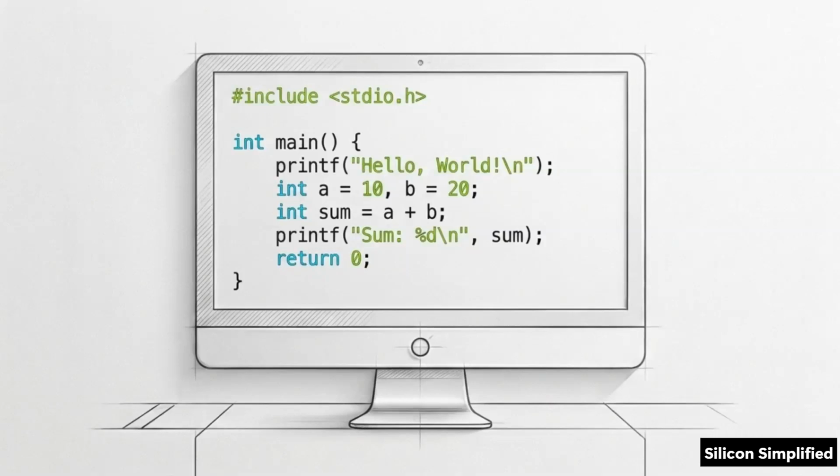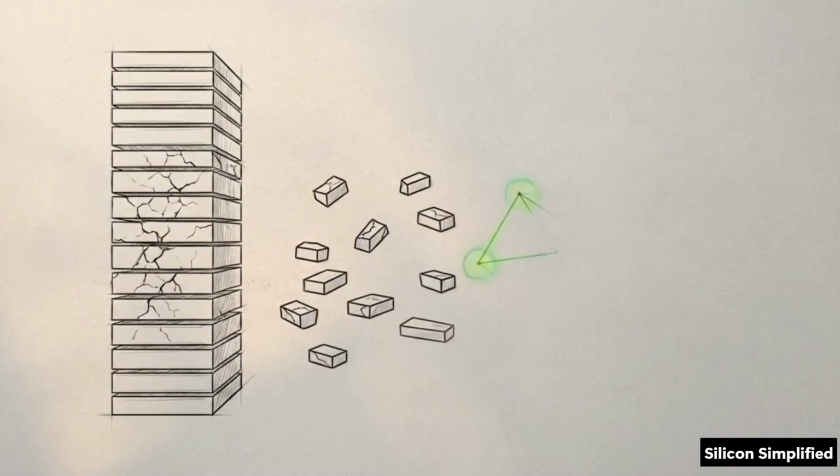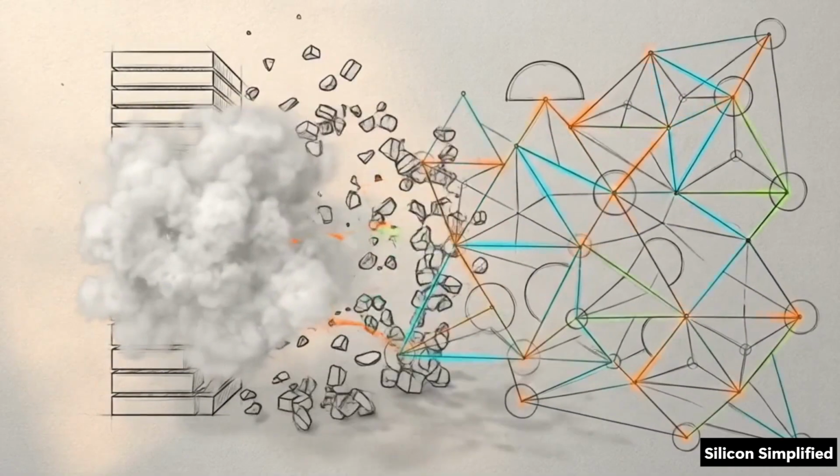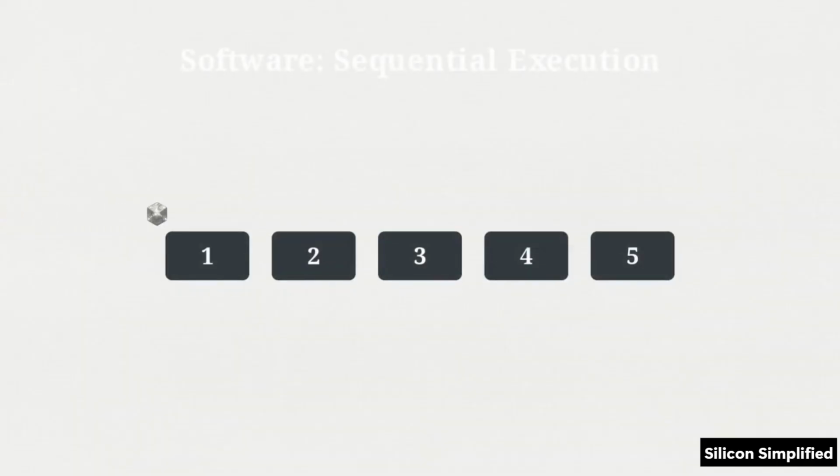When a software engineer first looks at Verilog, the syntax feels remarkably familiar. It looks like C, it reads like C. But assuming it executes like C is a guaranteed way to break a design. In a traditional programming language, a subroutine is simply an isolated thread of logic. The processor reads it, executes it line by line, and returns a result.